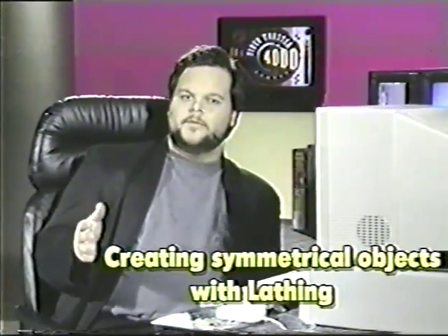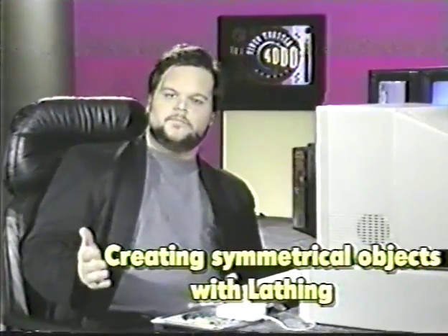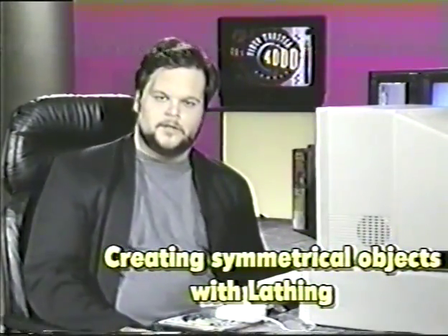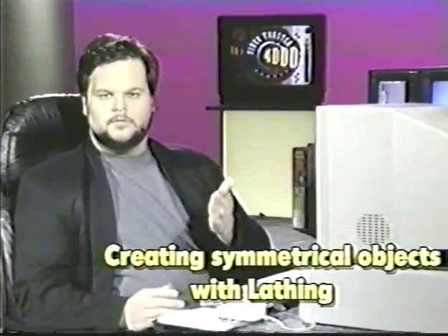Like I say, the number of objects you can make with this is large, and it's important to understand how these offset and angle tools work. Now, this is one use for lathing, and this is one way to do it, and it's very handy. But there's another use, and it's actually a little more common for lathing, and that's that you use lathing to create symmetrical objects. A good example of that would be an urn or a pawn from a chessboard, something like that. The way we use lathe here is very, very similar. We're sweeping it around. What we're actually doing is creating a half profile of an object.